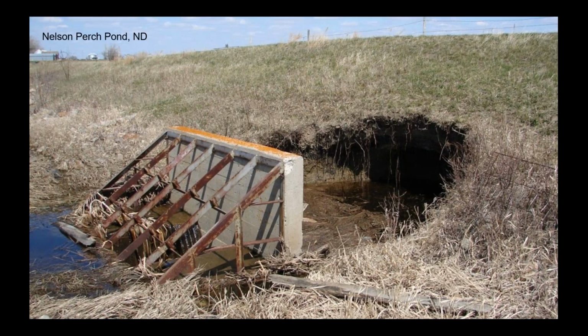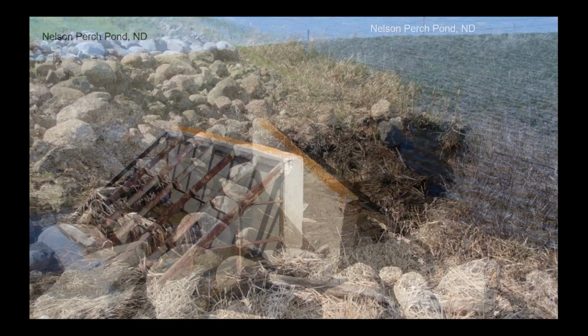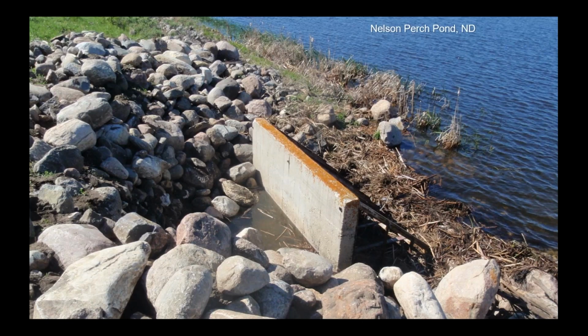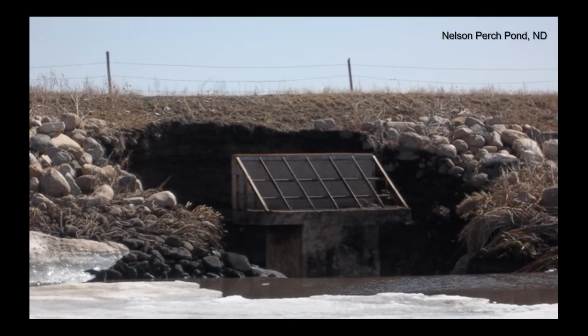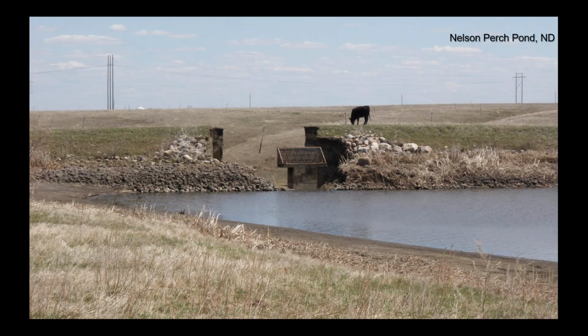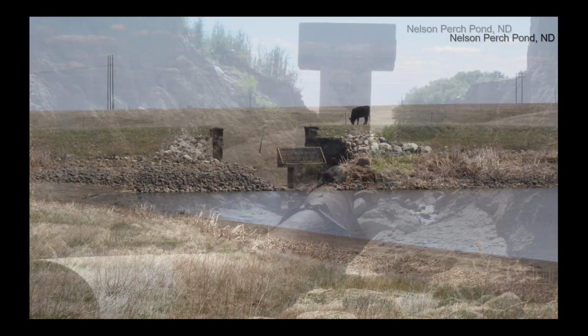And that's exactly what happened at this dam in North Dakota. So here's our inlet of the principal spillway, and the dam owner went out one day and he saw a great big sinkhole at the downstream face of the riser structure. So his solution was to go in and place some larger material, and did that, and then came out a little later and it was bigger, because he really didn't address the fundamental problem that was going on until the dam breached right through that location.